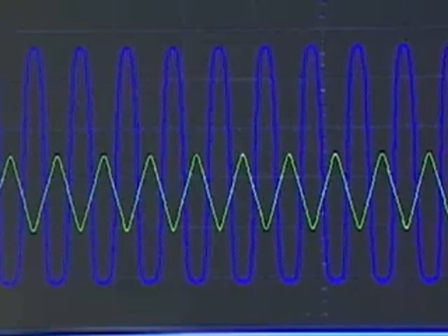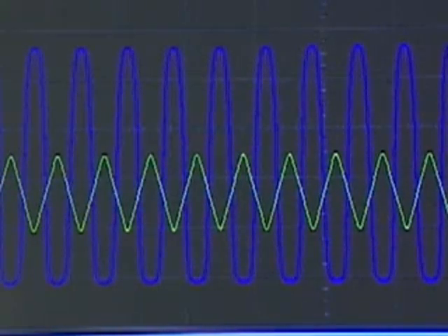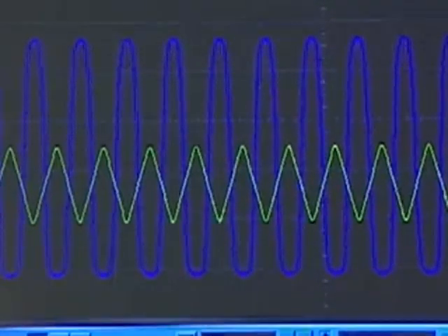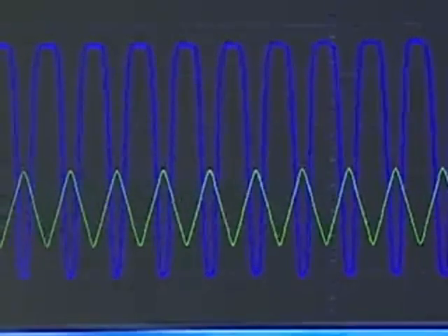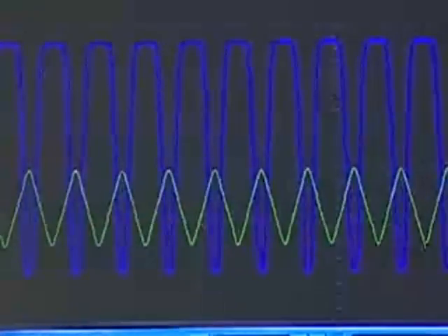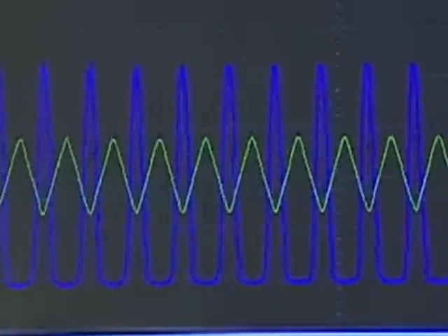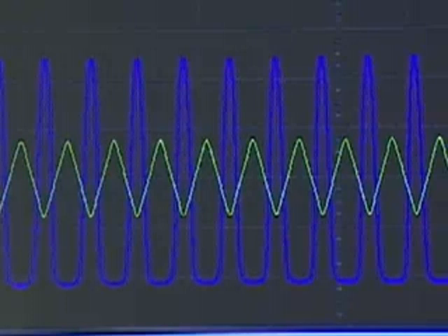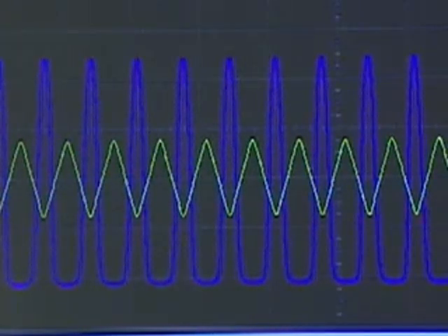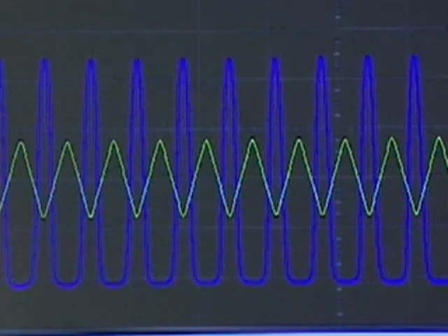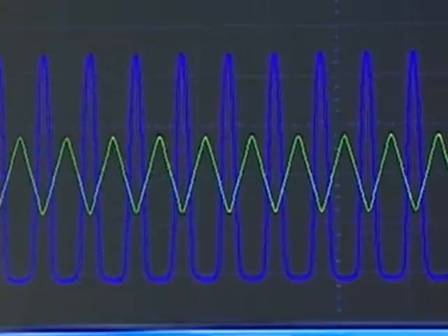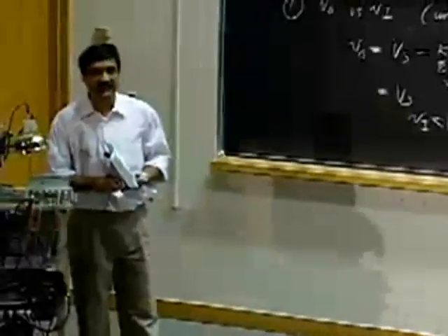Okay, so I showed you three things. One is very little offset. Okay, that was like so as the thing comes down. Very high offset, gets killed again, and the right amount of offset. Okay, but notice that we still have a problem, even with the right offset. The output is not linearly related to the input. It's nonlinear. And the answer to get a linear response is good old small signal stuff. And we'll look at the small signal part in the next lecture.